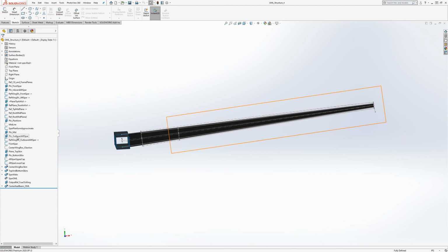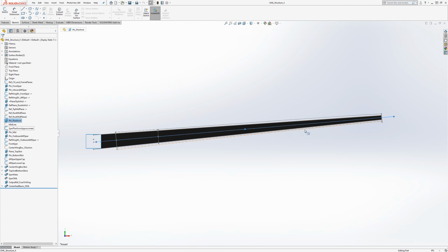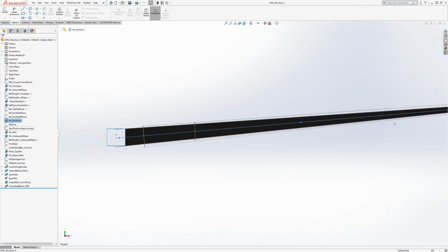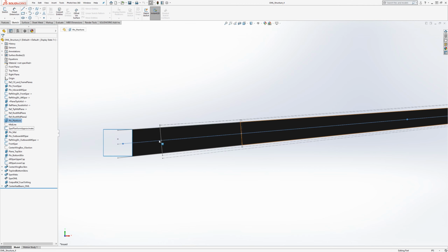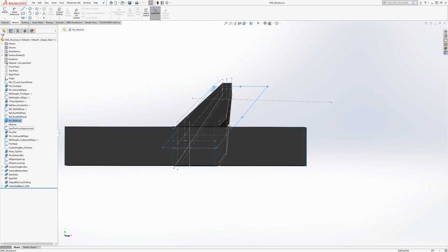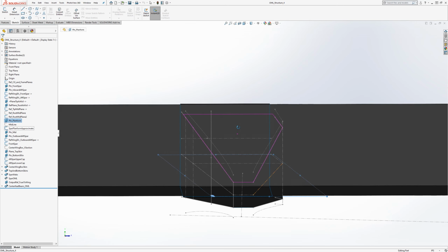So there's a separate planform plane that gets created inside the structure that's not exactly the same as the actual planform of that dihedral at 5-degree plane for the surfacing, but it's just here for maximizing the depth of the spar, so that we have at least enough clearance for ribs to be placed around the spar, all around its four corners.